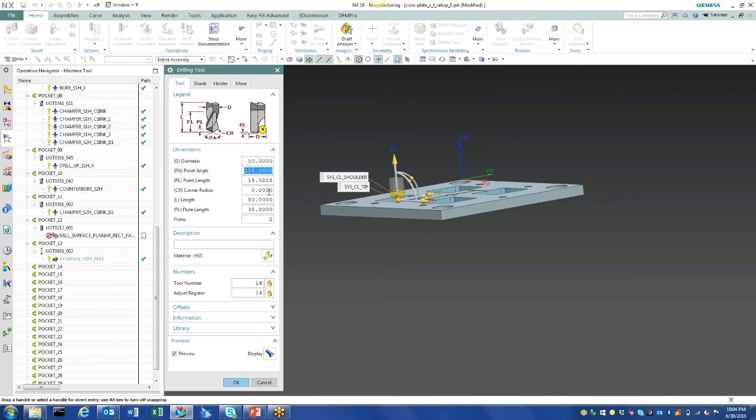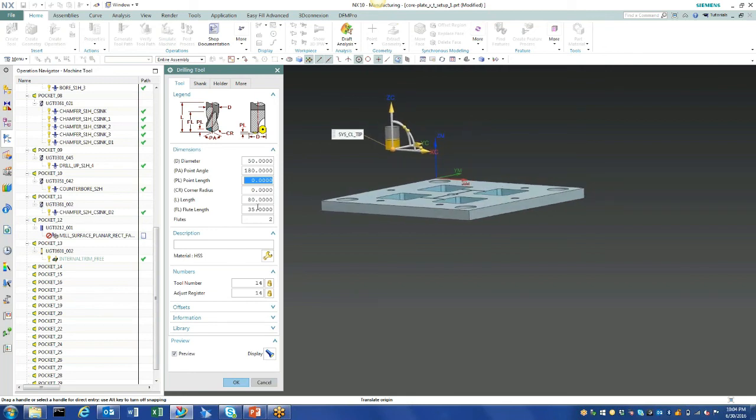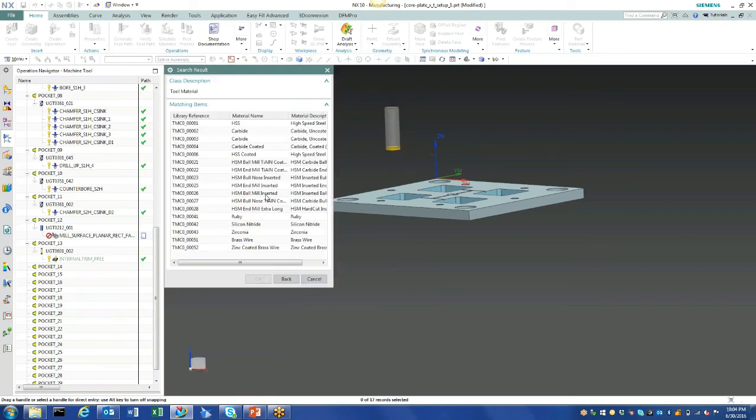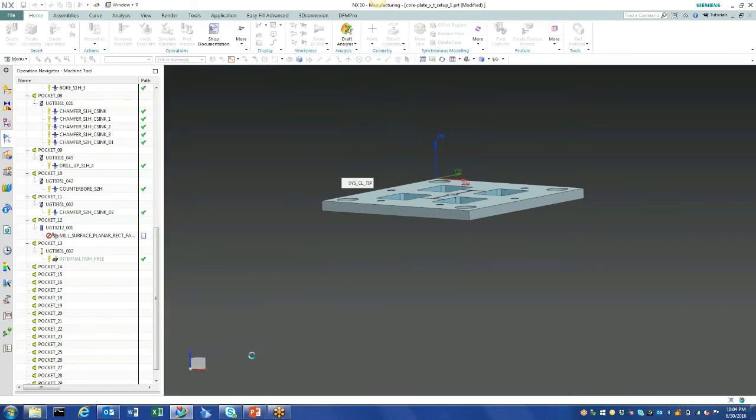We're going to make it 180. That'll be flat. We can go ahead and move this to see it. So we're going to make this length more accommodating, probably 150 is a more adequate length. This is going to be, we'll make this 10. The inserts are going to be about 10. This is going to change to carbide for our speeds and feeds.